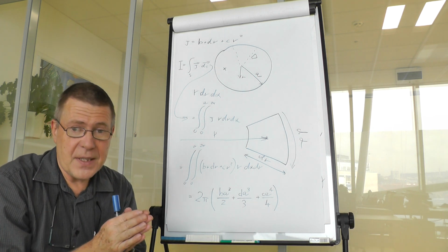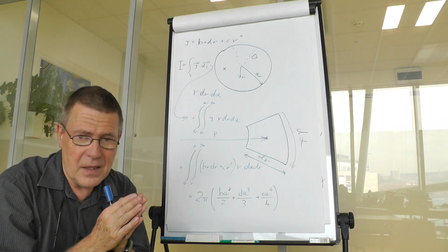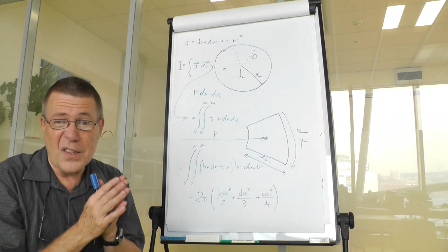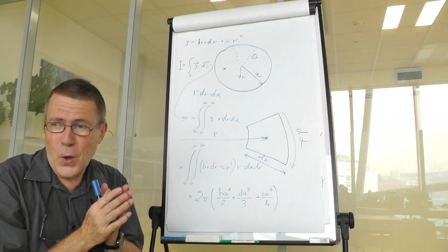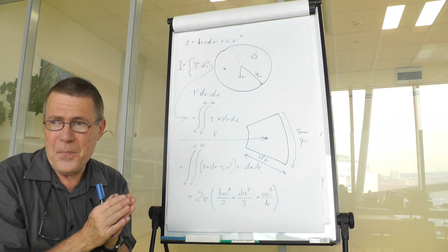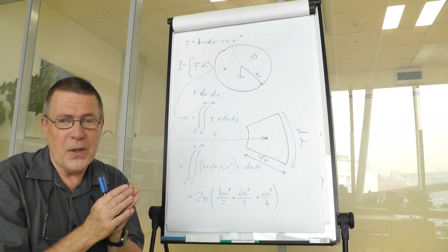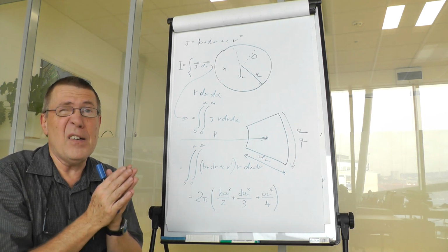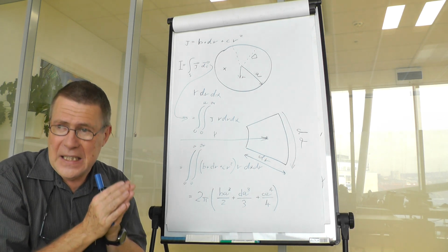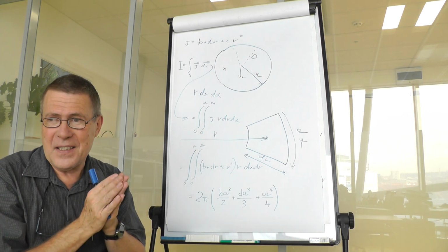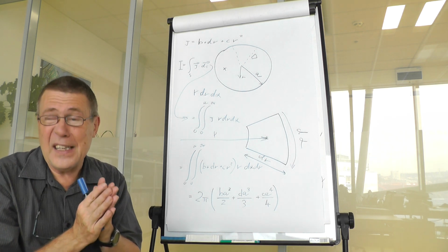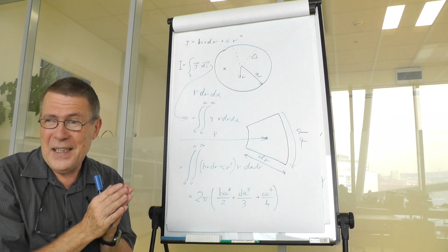For some applications, typically with AC currents, typically with high frequency AC currents, we can consider only current flow on the surface of conductors. The current that does not enter the conductor significantly. And therefore, the inductance value is only affected by magnetic flux that flows outside of conductors. This is called external inductance. And we have established a value of external inductance of a coaxial cable just today.